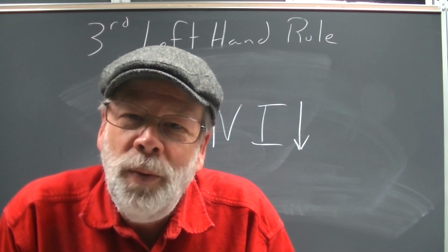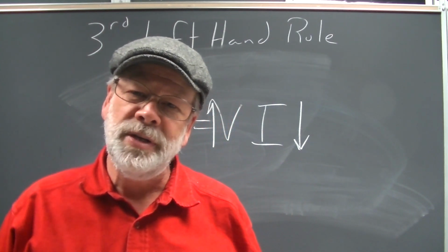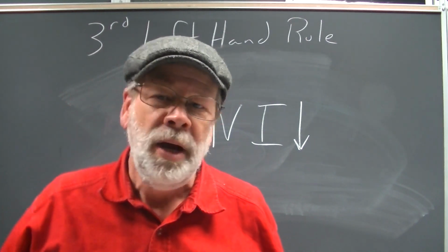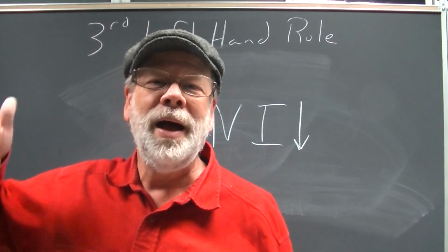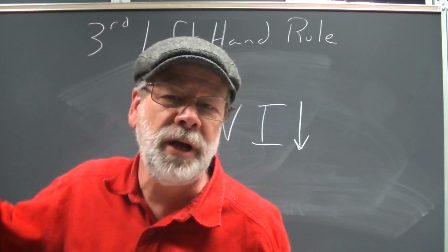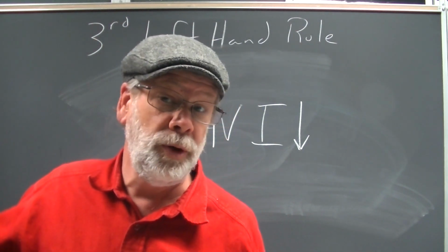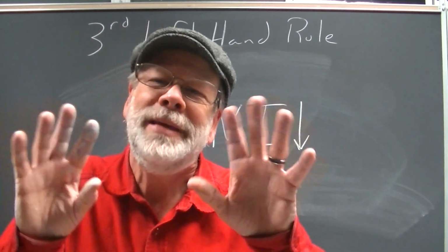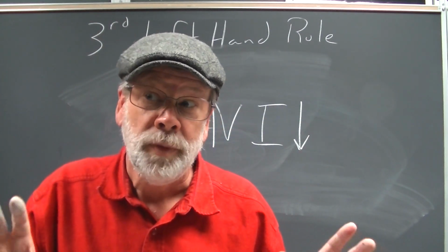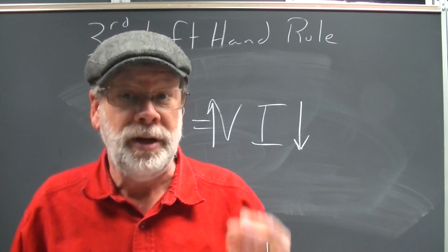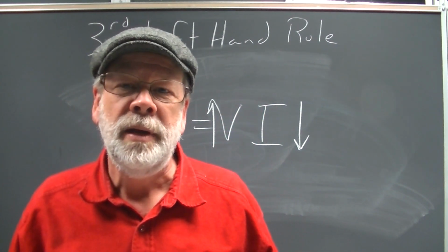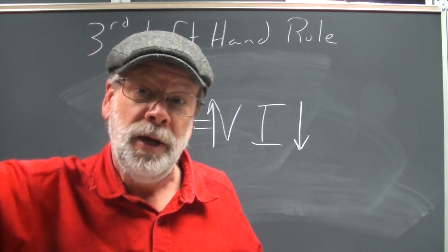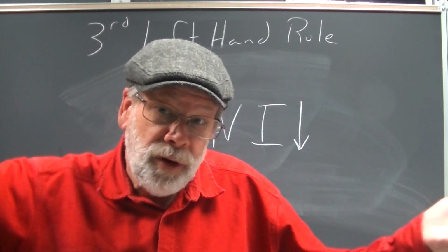And that's what we do. When you have a power generation station, we put it through that transformer and we step it up. So we might make the voltage 10 times, 100 times greater than the voltage being produced. Well, that would make the current 100 times less. Now, yes, there's going to be a little bit of loss, but still, it's going to make the current enormously less. And then we send that high voltage electricity to wherever we're distributing it.